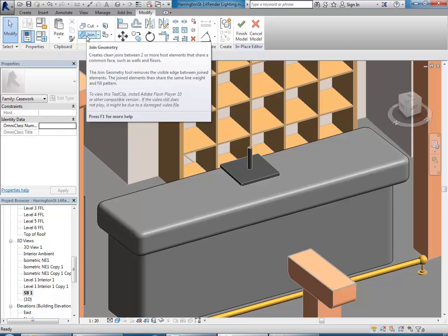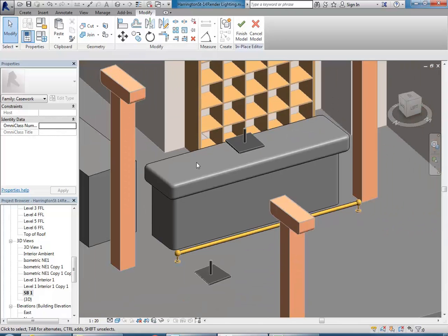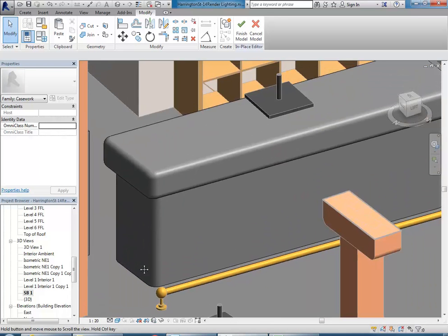Countertops are a common thing where you'll need rounded edges, and gutters, skirtings, cornices, all of those things follow the same principle. So it's really just thinking about the profile that defines the shape or defines the form, and the plane that profile needs to be defined in before you go ahead and do the path or the axis, or even just set up the extrusion.